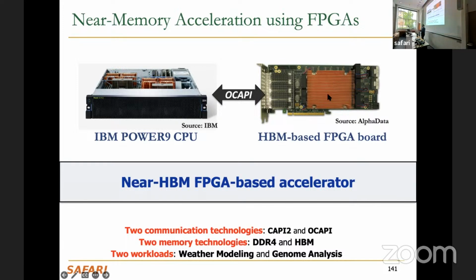One is you have access to very high memory bandwidth because you have HBM over here, right? And also you can customize the hardware to the function, right? Because of the FPGA reconfigurability. Clearly, it's not perfect customization because it's programmable reconfigurability. So there's overheads in FPGAs in general compared to an ASIC or a fixed function accelerator, but it's still better than what you can do in a CPU.